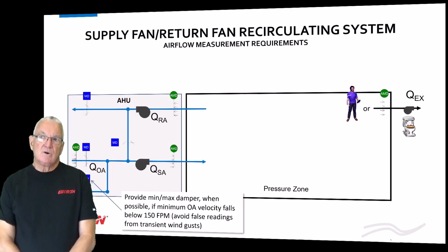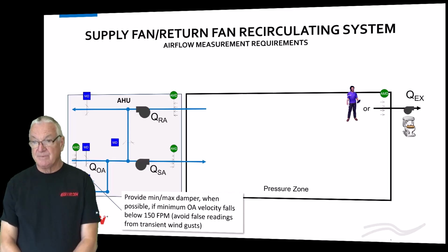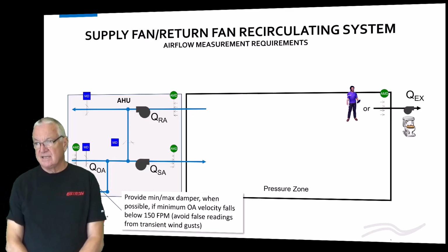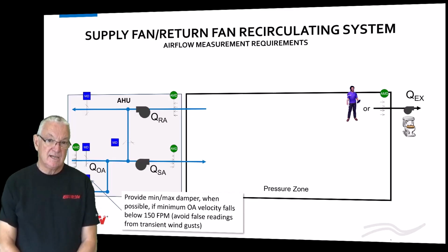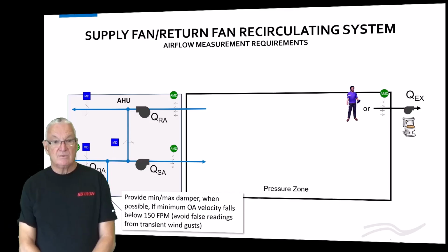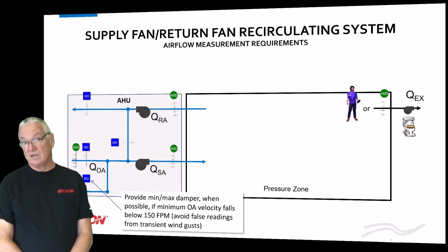To get to a lower flow, basically, moisture eliminating screens are mechanical wind dampening filters, as are regular air cleaning filters. And there are a lot of outside air intakes I really encourage people to think about using filters on, because the outside air is so filthy. Okay, I mean, if the outside air is so filthy that when you look at your outside air intake a year after you install the unit and it looks like a chia pet, you've got to ask yourself, do you really want that air coming in the building to improve air quality?